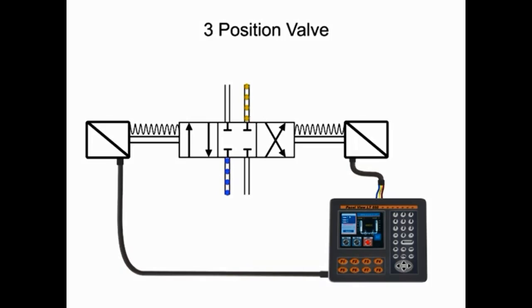As before, energizing both solenoids at once may cause damage to the valve or to the system. To prevent this from occurring, electrical circuits should be designed to make it impossible to have current on both solenoids at the same time.